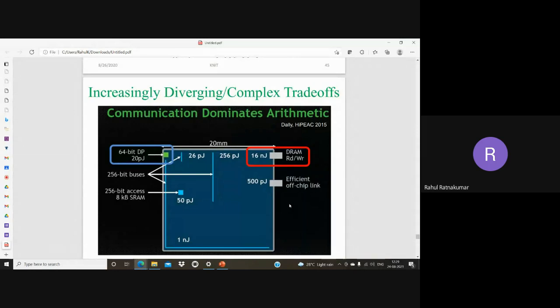So how to reduce the power dissipation in data transfer? That is another challenge. And one of the main reasons of this is the wire length. As the technology is reducing, or transistor size is reducing, the conductor size, which is maybe copper or even sometimes silver or aluminum, is also reducing. So as the area to conduct reduces, resistance is increasing.